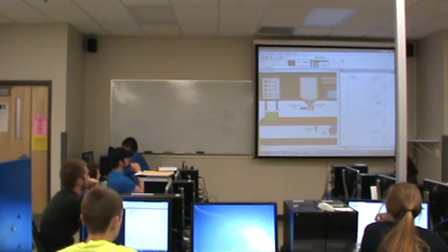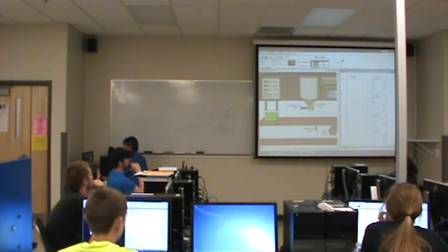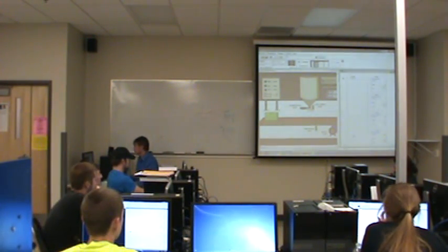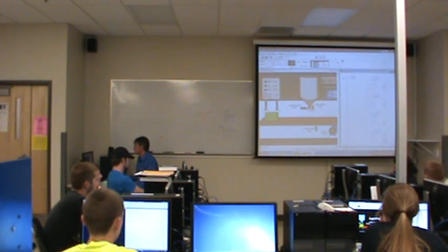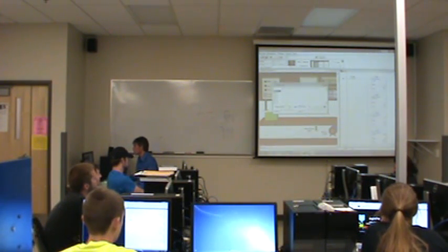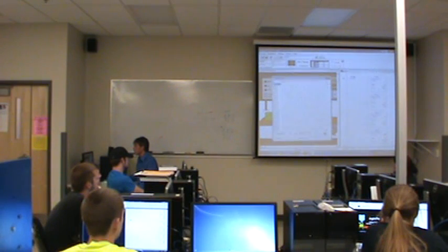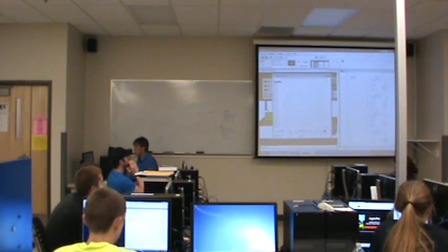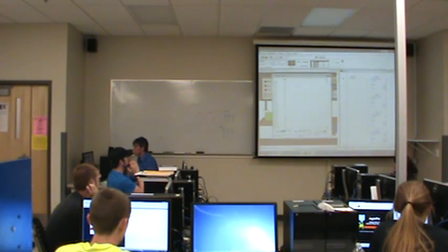All of these masks will be 24 because the only two inputs I'm ever interested in looking at are bits 3 and 4. Now, what do I want to see? Well, here's where I'm going to cheat just a little bit and save some time. I've already programmed in the bits. I don't want to go and compute the decimal value of all these. I'm going to let the software do it by hitting decimal. I want to look for 0, 8, 24, 8.